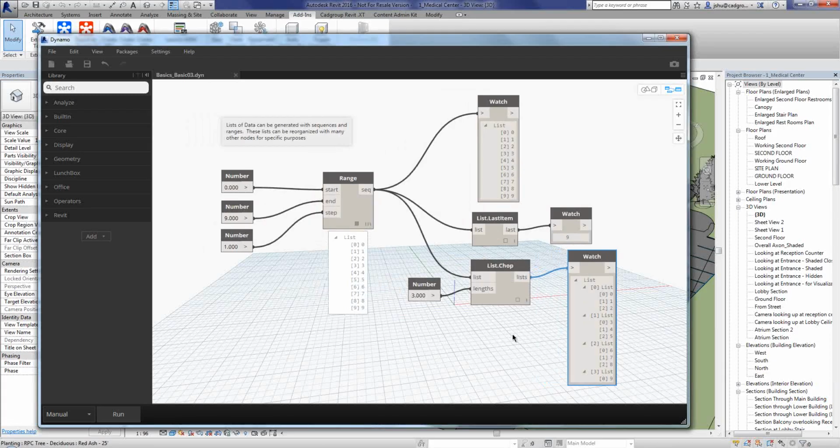Something that's quite unique with Dynamo is this list management. Because when we're using Revit, placing families or curtain panels manually, we are using our hands and eyes to finish the task. But when you're trying to use Dynamo to automate this process, list management is something that enables the program to automate a lot of those tasks without us pointing and clicking. So making the list appear in the correct format and showing the right data is crucial for Dynamo and Revit to integrate seamlessly together.